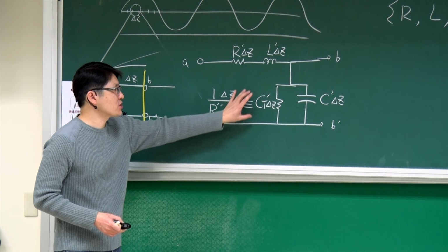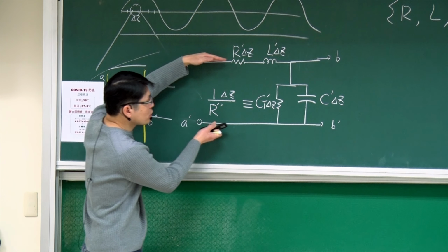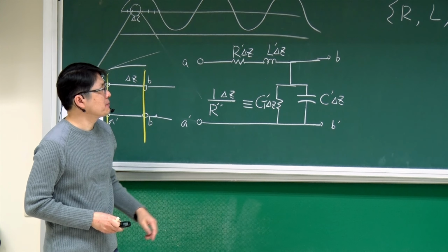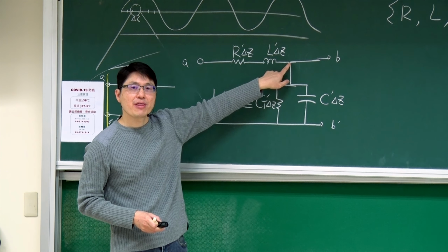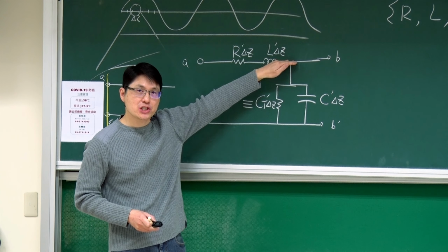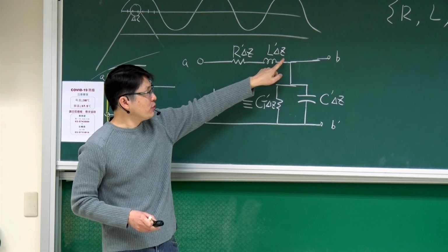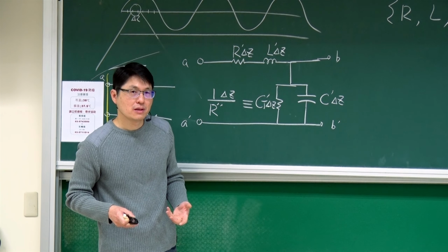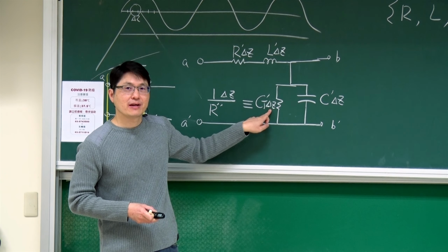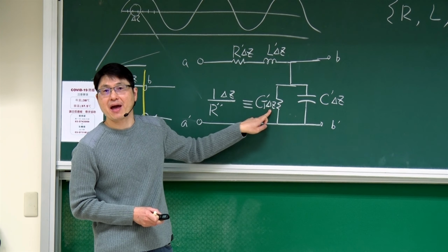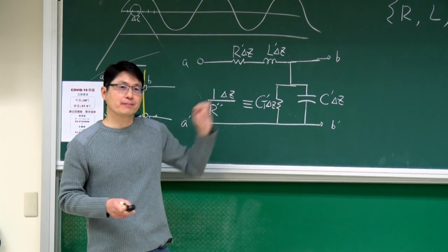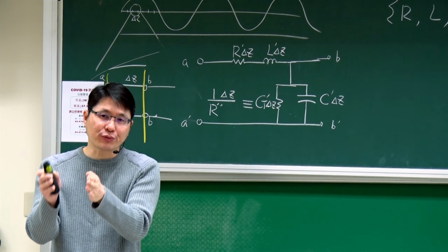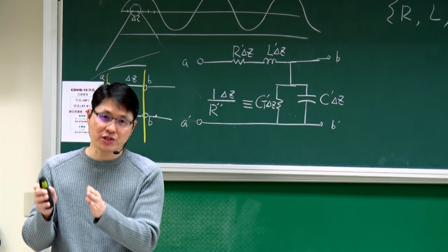Why am I including this term? Because although these two wires are acting like independent conductors, sometimes current can leak through from one conductor to the other. If you can have current conducting, that's called leakage, 漏电流. And then correspondingly, you would have a conductance in that path. So this is the proper lumped element circuitry for a differential length of the transmission line.